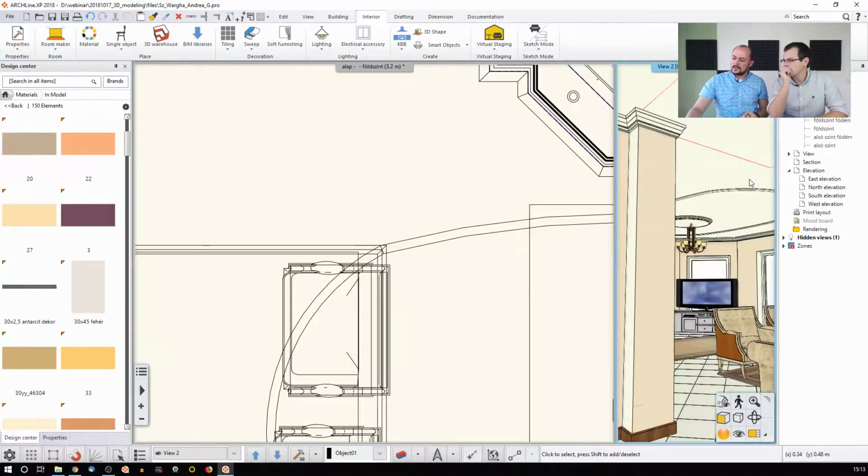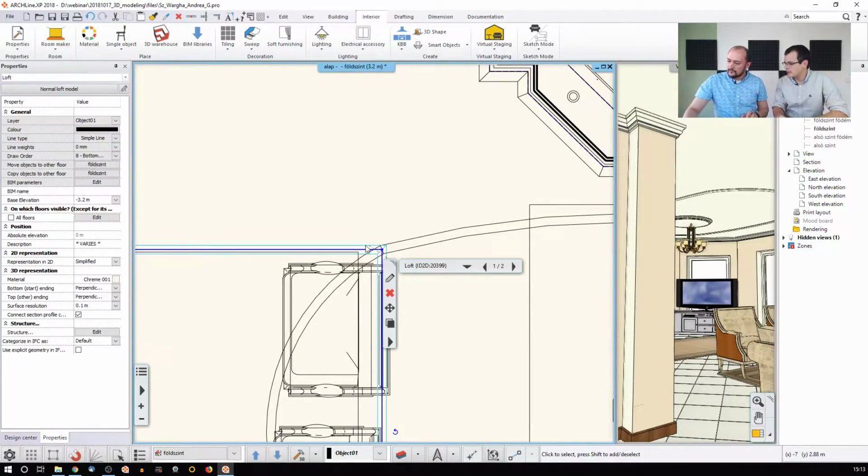But I cannot see it in 3D, because when you design in 2D, items are expected to be created on the floor, the default value, which is usually the 0. I see, so it's on the floor. It's around the carpet, right? Yeah, around there, I believe. It's even way below that. I don't know what the value is; I could measure it, but now I would like to show you a perfect tool to align them. Let's elevate it to, I don't know, 2.5.